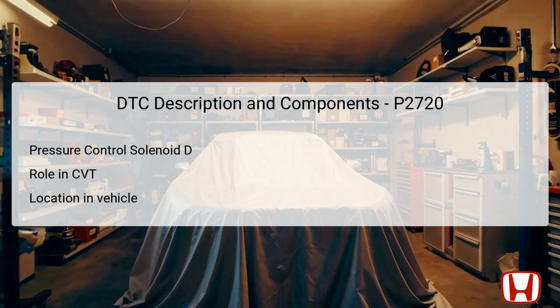performing diagnostics or repairs. An error like DTC P2720 indicates that the PCM has detected a low circuit signal from this solenoid, prompting further investigation into the electrical pathways, connections, and components that interact with it. Understanding this system's function will be critical in tracing the fault accurately.